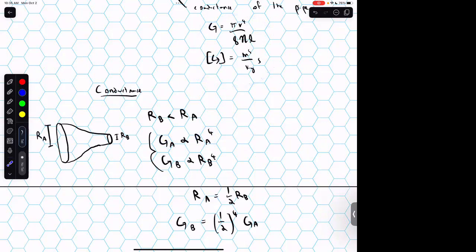And we've seen a couple of problems like these before. I know that with the Kepler's law stuff, they use these kinds of proportionalities all the time. But this is a whole genre of problem where they'll tell you that your radius went from this to this by some fraction, and you basically have to just propagate it through and see how it changes. And the important thing is to remember what the scaling of the one thing that changed was. Okay, and the big takeaway here is that I only changed my radius, but I got a really dramatic decrease in my conductance, and thus I should expect any flow rate to decrease as well.